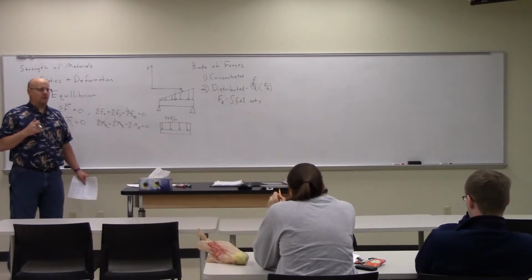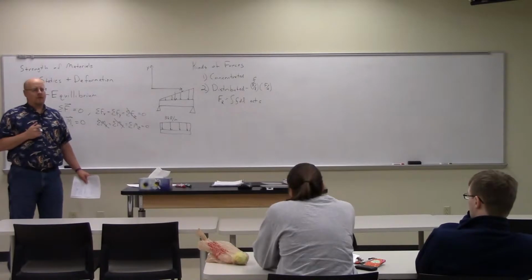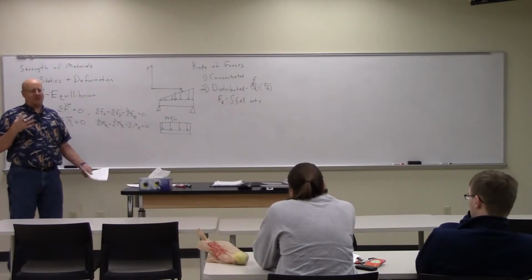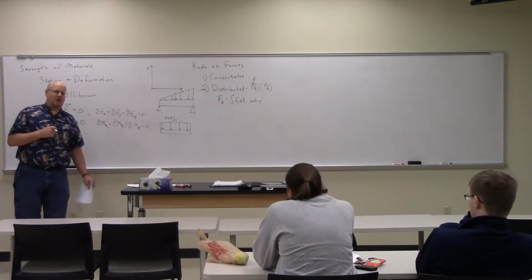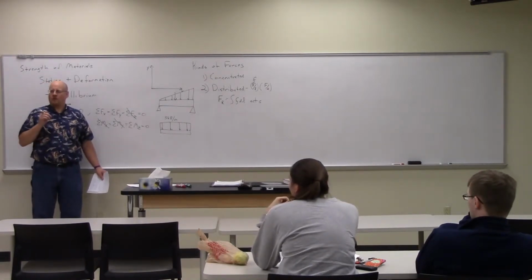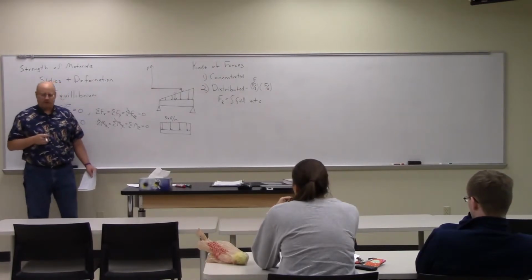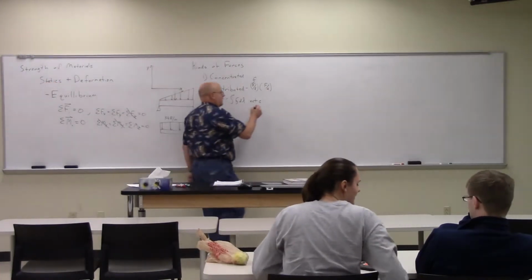If it's the straight line in the middle, it's the triangle, it's 2 thirds. Okay, but how would you define that in words instead of picking those particular locations? The particular word I'm looking for begins with a C. Centroid. The force is applied through the centroid.